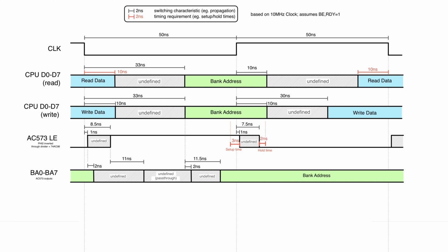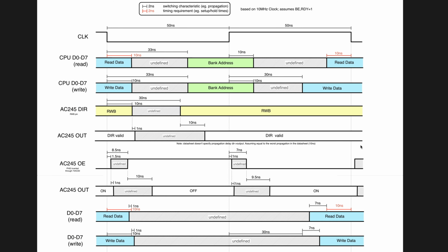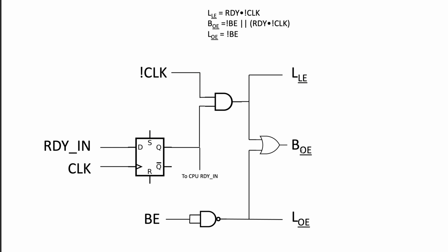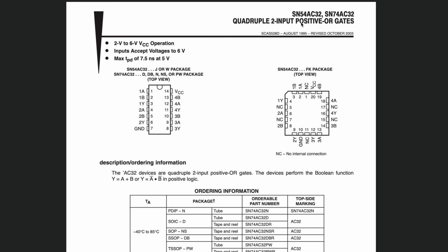And so that's because we ensured that there was only a single gate between the clock and the latch enabled signal. So now let's take a look at the buffer. So this is the timing diagram of the buffer where we left off the last time. And for this signal, we have the same AND gate, so the same 74AC08, and we also are going through an OR gate. And for this one, I'm going to use a 74AC32.